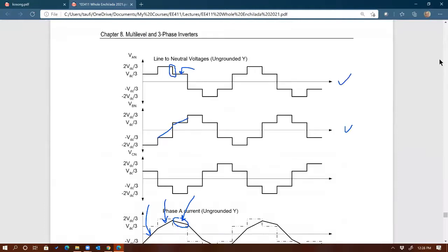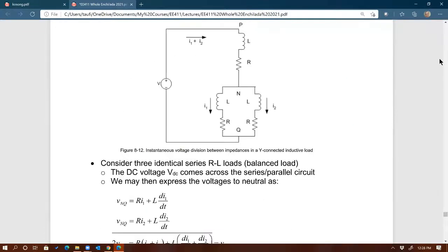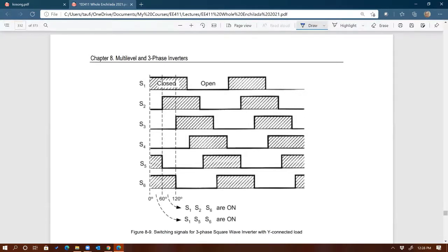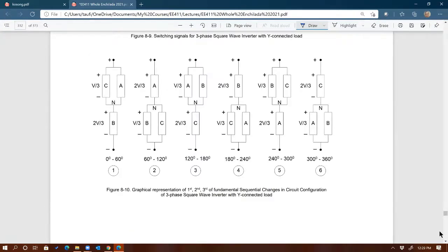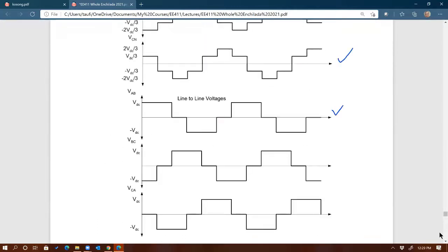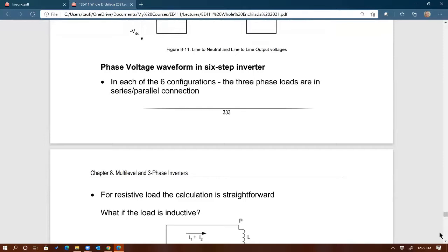There is no alpha. They're all like 50% duty cycle. That's correct. Exactly. So this is a different type of inverter. This is a 6-step, 3-phase inverter. What you're referring to as alpha is the multi-level. I keep saying multi-phase, multi-level. It could be single phase, it could be 3-phase. Yeah, but that's multi-level.